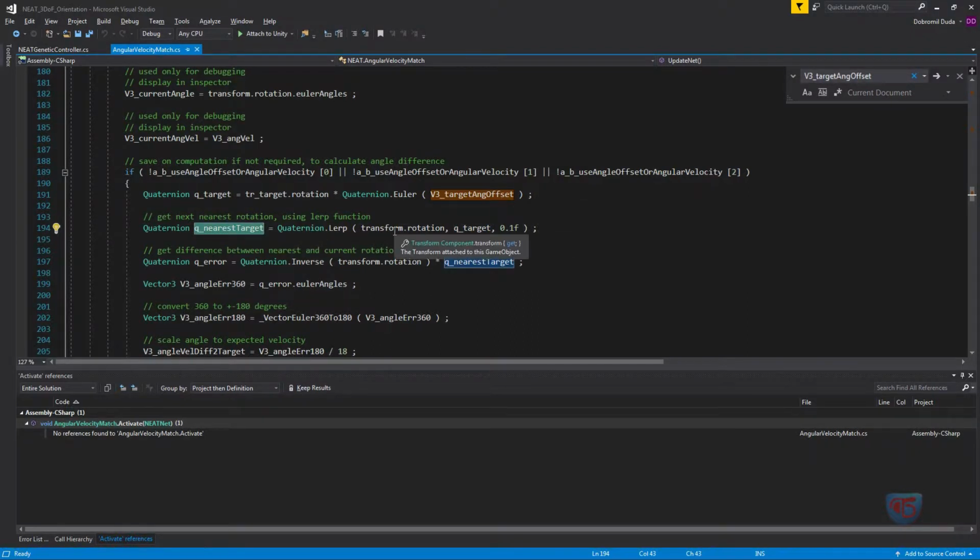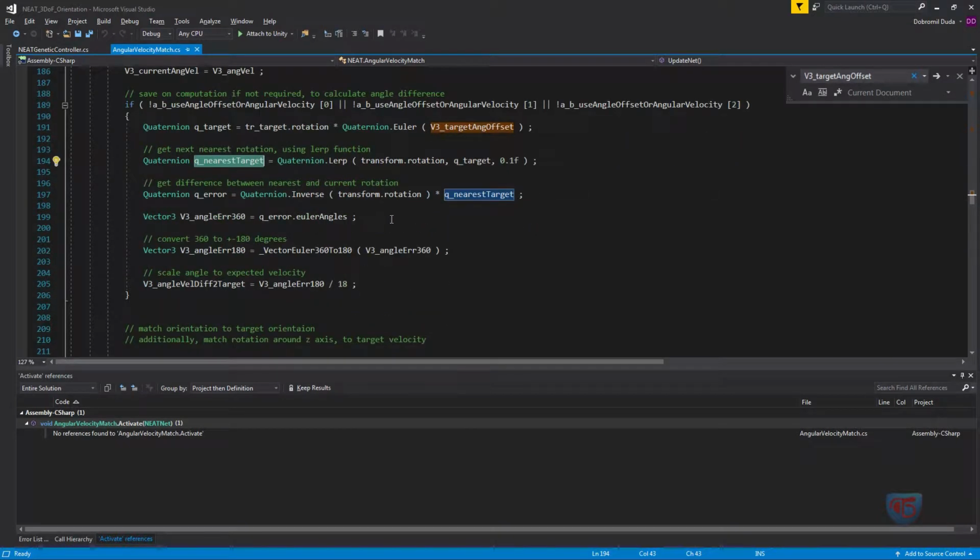So we got 180 degrees divided by 10, that's 18 degrees, because this is 1/10 of it. But if you got 18 degrees of rotation to the target, then you got 1/10 of that, which is 1.8 degrees, much smaller steps. And I found this way to be the best, after a number of iterations of scripts I had in the past, to achieve the best performance of the system.